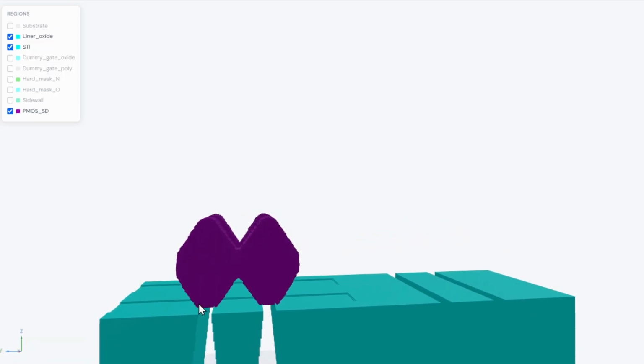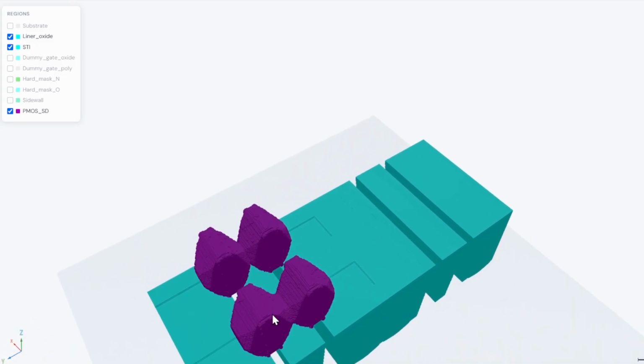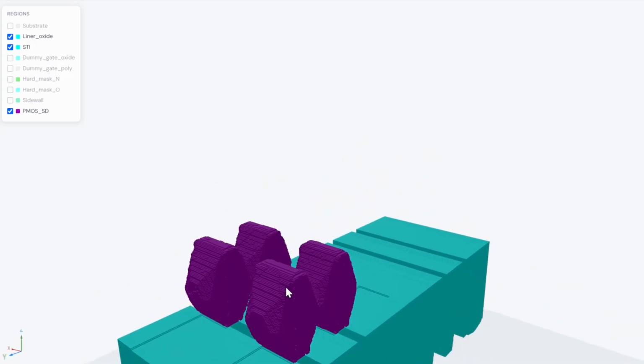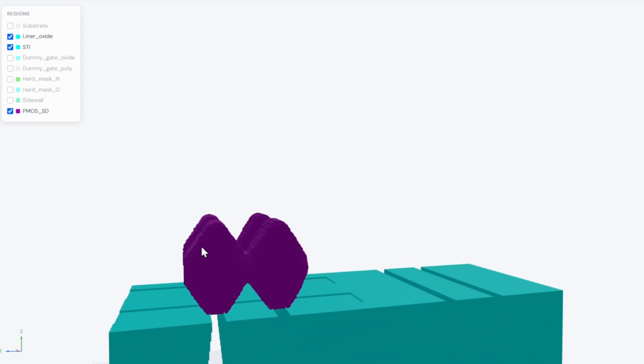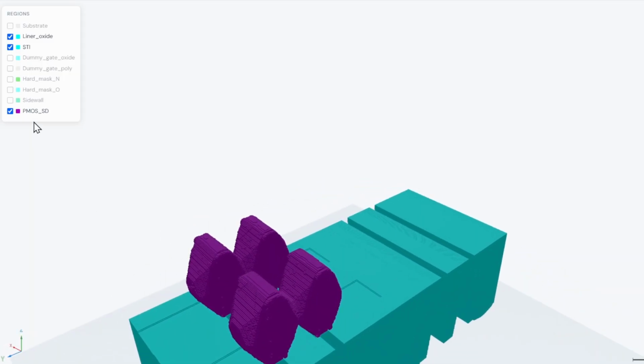Here we have a bottom and one segment, another segment, and another segment, and another segment. It is known that the shape of a silicon germanium layer grown by selective epitaxial growth looks like a pentagon. If we allow even further growth, then the rounded corners will eventually become sharper. But we have stopped here.